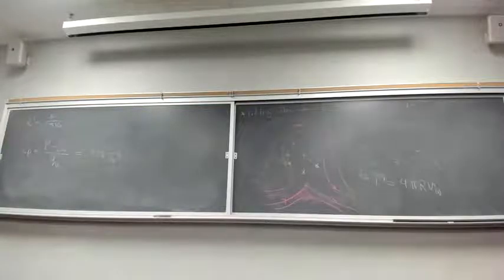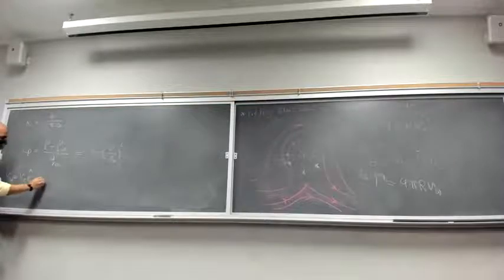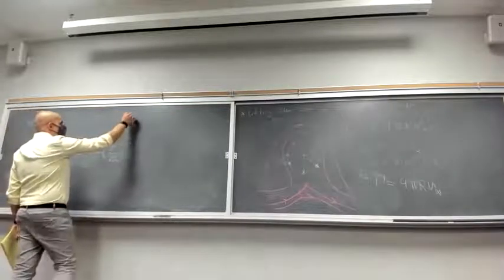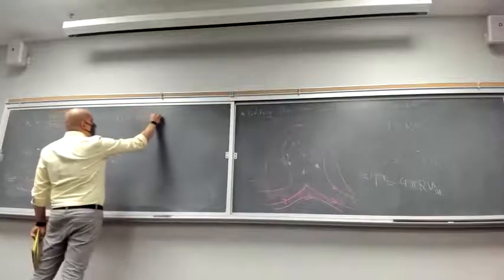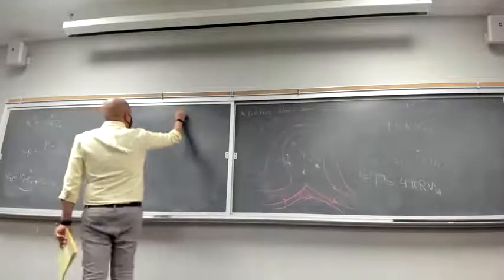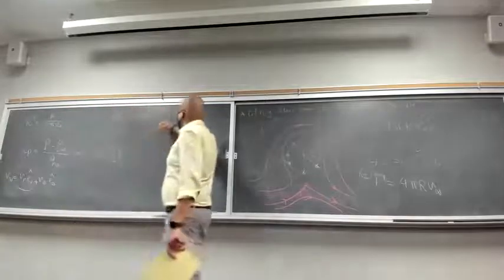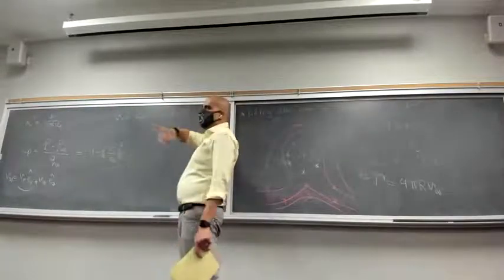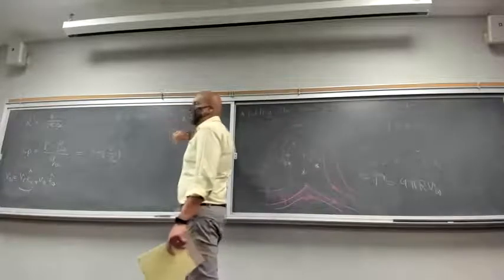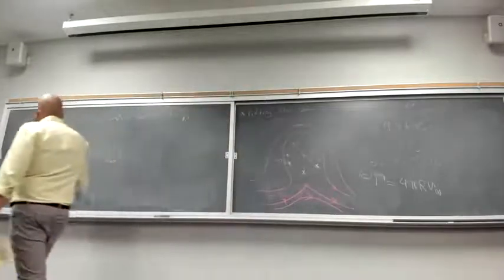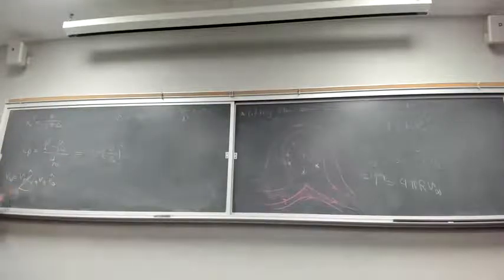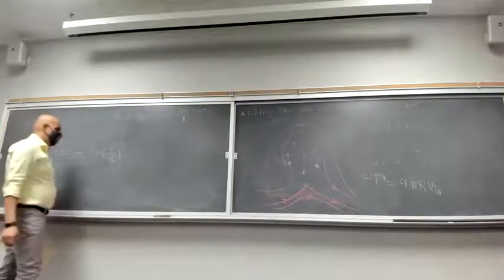And the velocity on the surface is V_r e_r plus V_theta e_theta. For V_r, if I remember correctly, it was V infinity cosine theta times 1 minus R squared over r squared. So on the surface of the cylinder, V_r is always 0, because your r is going to be capital R. So this part is 0, and we have V equals V_theta.